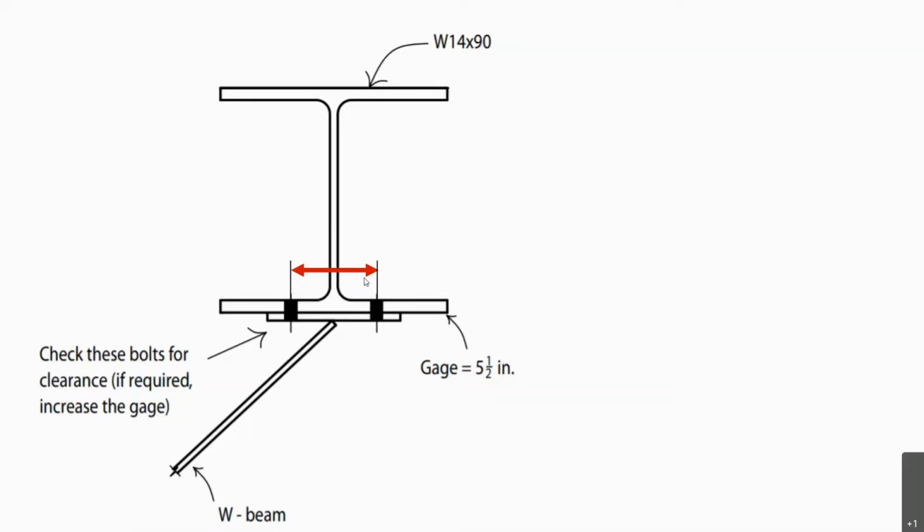In the old days, punching or drilling of the holes would be tedious if the gauge size wasn't standardized, and the need to adjust the gauge distance in the punching or drilling line really slowed things down. Today, it's not as much of an issue, but still using a standard gauge for each shape may save the designer money. But other gauges can be used if they satisfy the edge distances, spacing, and entering or tightening clearances.